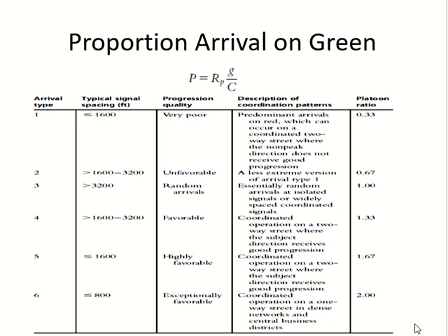Okay, effective green, yes, effective green. Green time or the phase time minus lost time. And capital C is the cycle length. And how do we define cycle length? Tell me. Cycle length is what? Red to red. Okay. Summation of all phases. Summation of all phases. Very good. Everybody is woken up now.